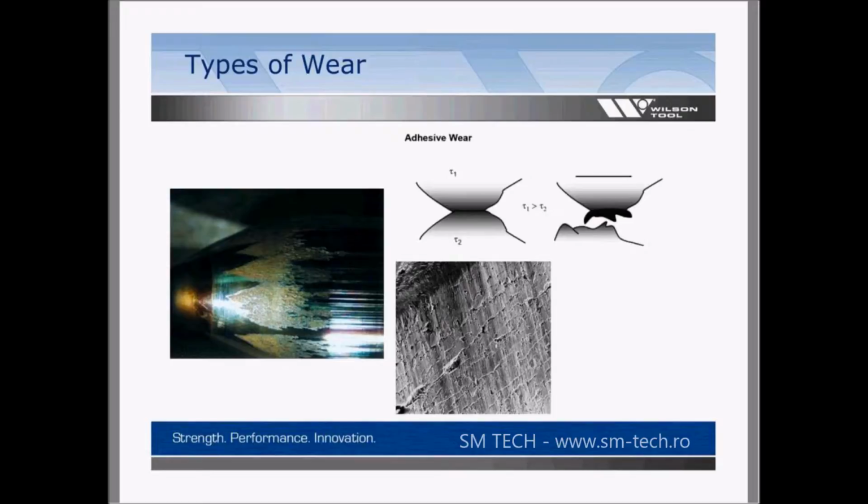This adhesive wear here occurs when the material being formed transfers to the tooling doing the work. As you see on the left here, the drawing process of the form is picking up material along the radius where it's being drawn or formed, where all that pressure of the material is being put on. Increasing that hardness and machinability of the steel are important. Surface finish obviously is very critical in the drawing process. So having material that will machine consistently, wear evenly, and polish well are very important.